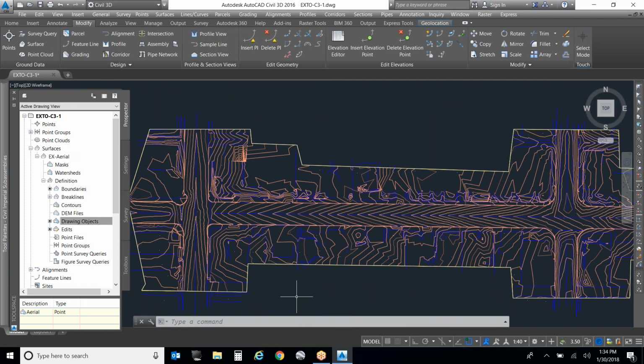Well, in those pothole information, the place where you're going to be using that the most is going to actually be where the utility is underground. But you're also going to get a surface shot. One of the things you can do is compare those surface shots to your aerial and see how close it is. And if it's good enough, then you don't have to do that extra work of doing the composite or whatever.